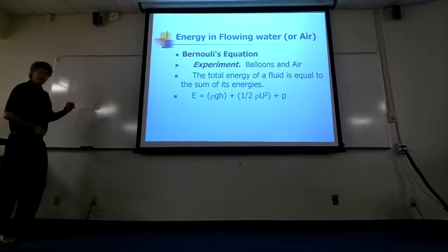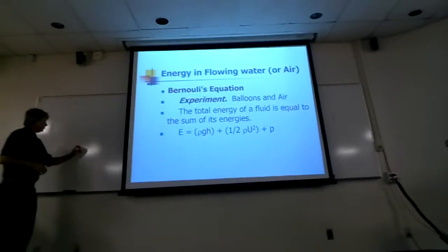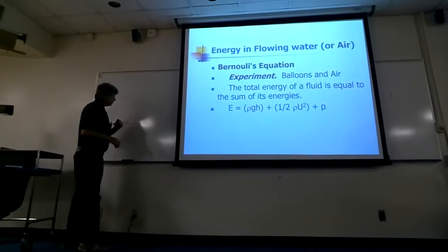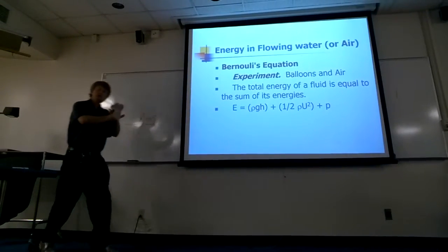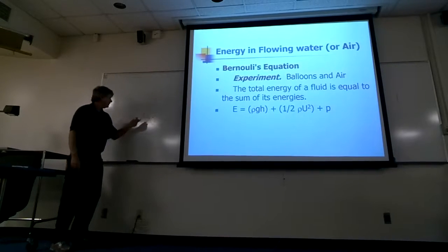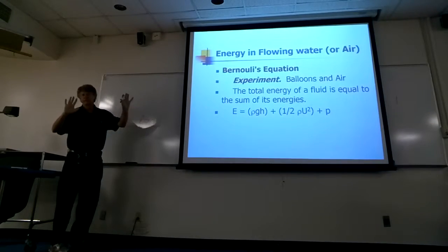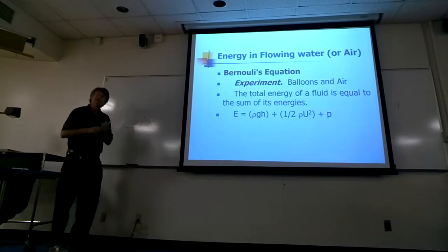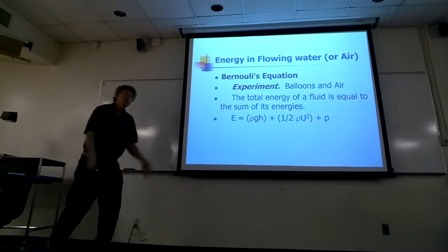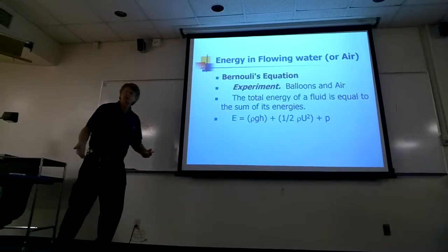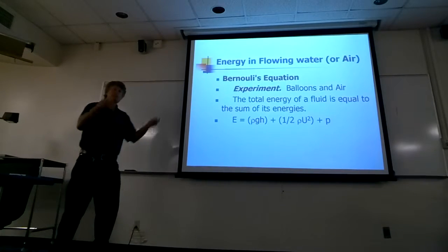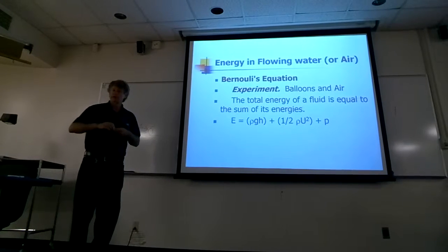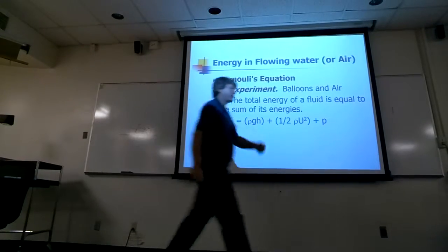There are what we call viscous drag effects, which is basically you've got the water and it actually will push on a rock or pebble and kind of push it down the stream. With really big rocks in the middle of a river, this is a big effect. But for most sediment, it's the Bernoulli effect that's the most important thing that entrains sediments, pulls them into the flow and starts them moving downstream. Okay, questions? So let's do a couple of trial problems.